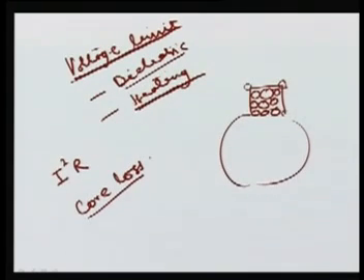No doubt if you raise the voltage, the current will be reduced, so that loss will be reduced, but the core loss will be increased. So we have to see how much we are going to heat the core and the insulating material, and how we are going to dissipate the heat generated in terms of core loss.